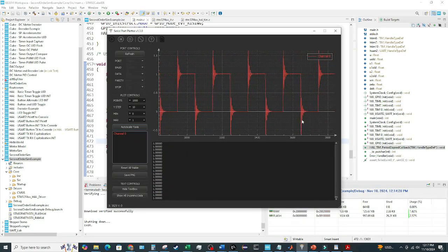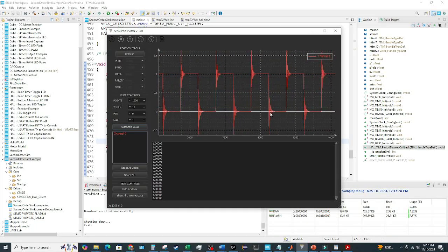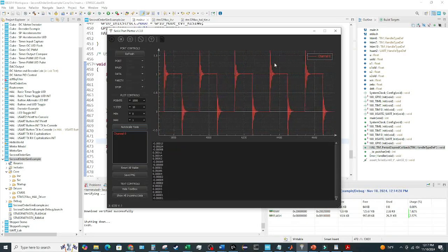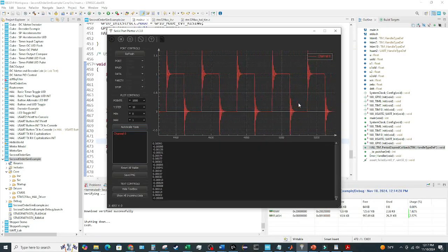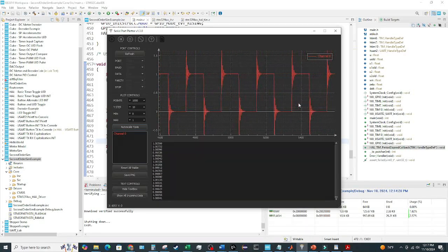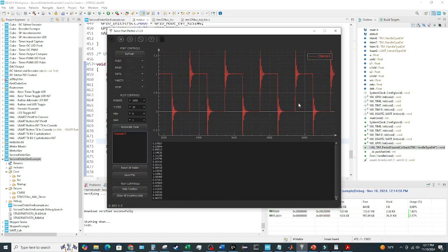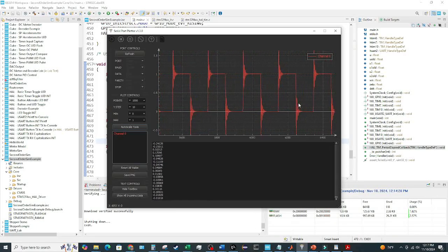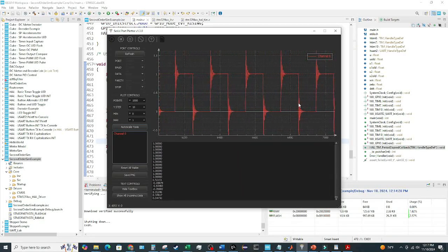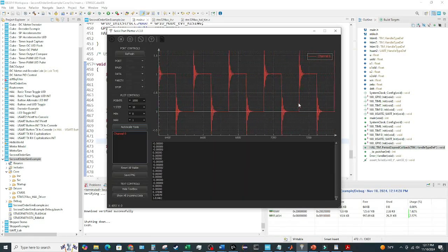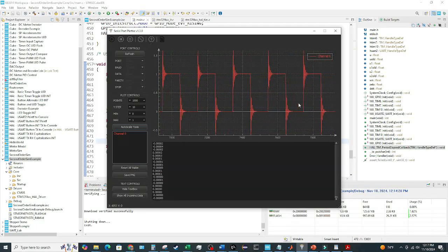It's toggling about every second, right? Our input signal is toggling every second. And we have a real high ring, right? There's a lot of overshoot, a lot of oscillation. So you can imagine that the locations of our roots are going to be such that it's changing very fast. So those roots are going to be far from the origin, but also kind of close to that j omega axis in the s plane, because our sigma is negative, but maybe not very negative because there's a lot of oscillation.